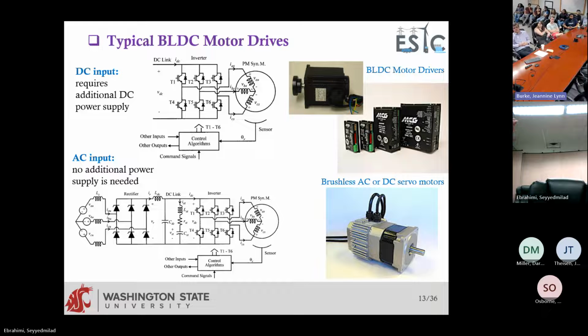But let me ask you a question. How can you control the speed of a synchronous machine? Let me formulate my question like this. I have a synchronous machine, and it's not spinning, of course. I put it on the desk, and then I connect it to the power outlet here. So it's 60 hertz, right? Do you expect it to move or not? Yes, no, why?